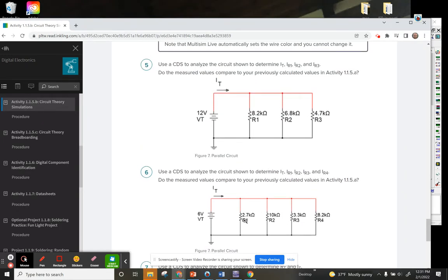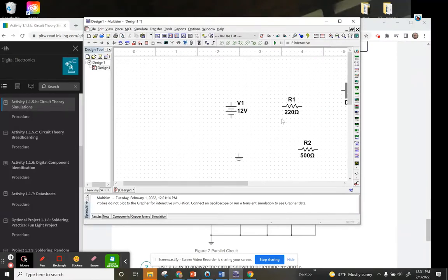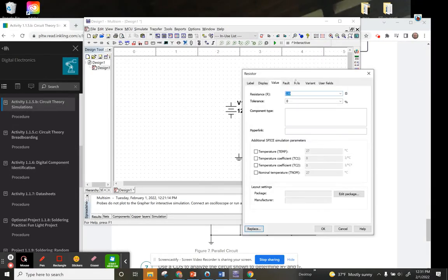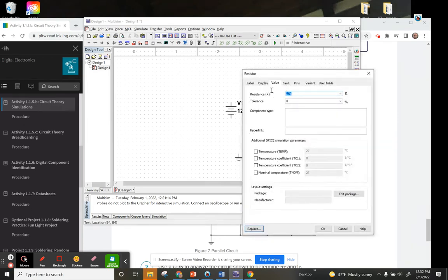Okay. So for these right here, this 2.7K for these larger ones coming in, they'll know that is for a kilo. You can also, when you're placing them, go ahead and search for that too. Or you could have searched for 2700 instead of 2.7K. All right, I'm going to go ahead and just turn that back to, let's just call it 1,000 or 1K.